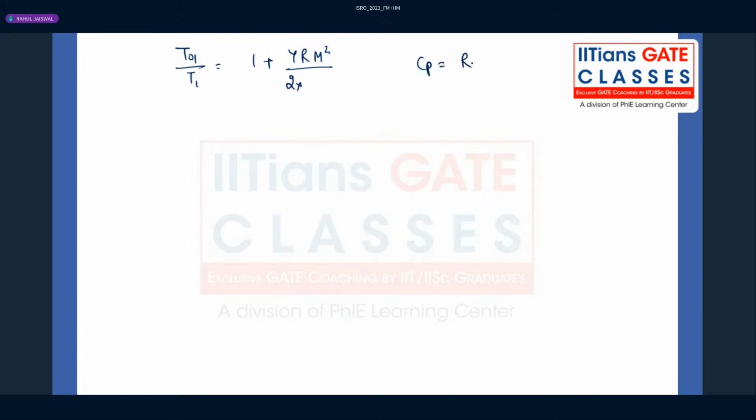We know Cp is R gamma by gamma minus 1, so gamma and gamma cancel out. T01 divided by T1 equals 1 plus (gamma minus 1) divided by 2 into Mach number square. That is the particular relation we have calculated.